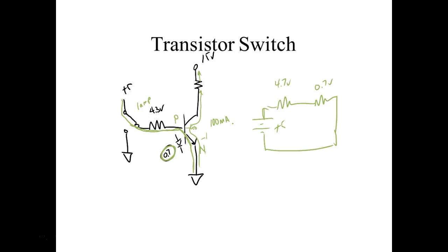So what we have to do is, even though your collector has an N, your collector has to be reverse biased. So notice up here we have a P, right? You understand? Relative to 0.7 of a volt. So basically your collector junction is reverse biased. But whether you understand it or not, we have to put a big positive on the collector. The emitter has to be negative in respect to it, right? You understand? And then we can turn this thing on or off.